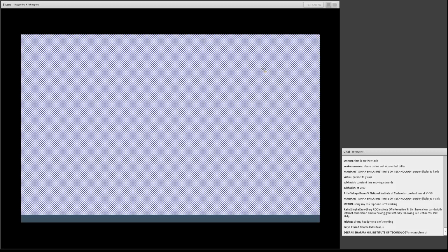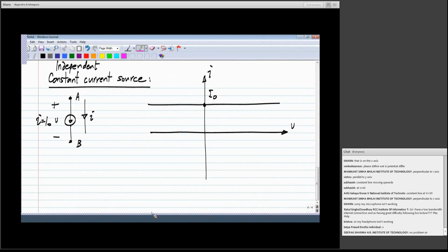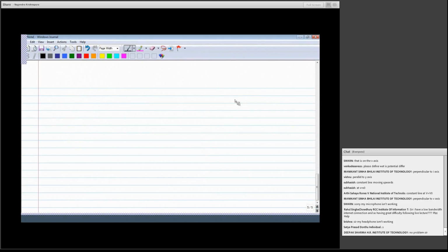Now the next basic element that we will consider will be a resistor. Okay, and as usual we define the voltage in some way. Now I have chosen A to be positive and B to be negative, but you could easily do it the other way. But what is important is once you have chosen the sign of V, you should be looking at I going into the positive terminal. Okay, now this is the sign convention that's universally followed, so that's what you must use.